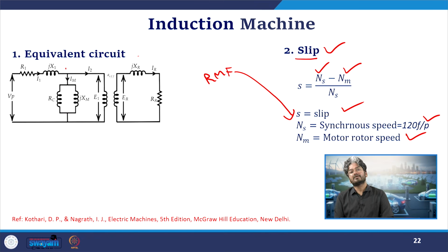So ultimately the torque will not be produced and the rotor will fall back because of the losses we have discussed. The other opposing factor is our load torque. So our torque production would become zero because of the load torque and the losses, and the rotor will fall back. So our motor runs at a slightly lower speed, such that the power to be delivered is generated by the interaction between the two magnetic fields.